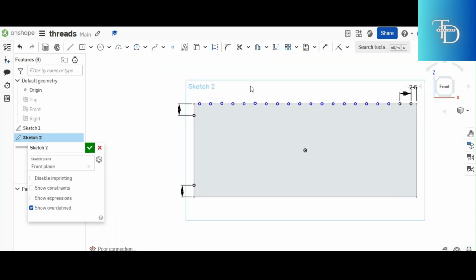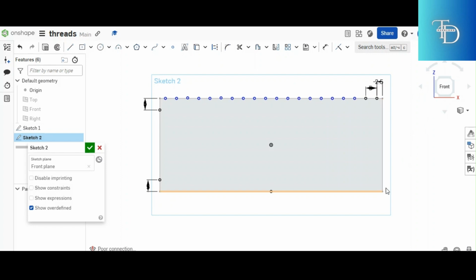And then the next step after that, you come to the opposite side, which is this side right here. On this side, you do not start marking a half pitch, because that half pitch is for deciding the direction for a right hand. You mark the half pitch on that part only. On this part over here, you do not mark a half pitch. You start by marking a full pitch, so you mark 5 units right there, another five, another five, another five, all the way up to the end point. And then let me clarify this.